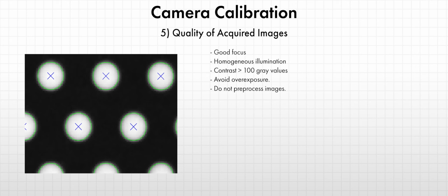Note that you shouldn't pre-process calibration images. This falsifies the results. To be able to reproduce the calibration and identify potential problems, it's useful to save your calibration images. Make sure that you use an image format that can be saved lossless, like PNG.